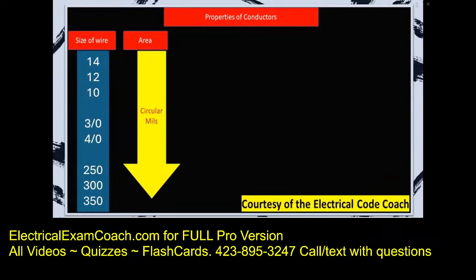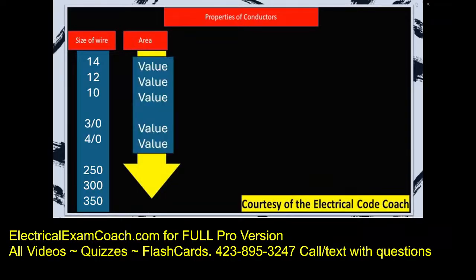You'll notice all of your familiar friends: 14, 12, 10, then it goes down into larger numbers like 3/0 and 4/0, then it goes into the KC mils, and that's where we get those circular mils from: 250, 300, 350. In the next column over, we need to be sure to be in the area section, because that's where we're going to get our circular mils value. Each wire has a circular mils value. And you'll notice for the first few wires that there's 2 sets of 12, 2 sets of 14, 2 sets of 10. But if you look over, the circular mils are the exact same size.